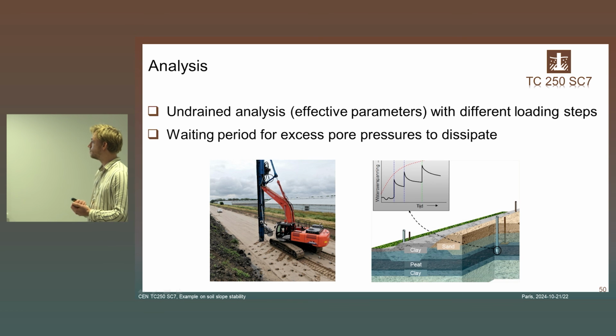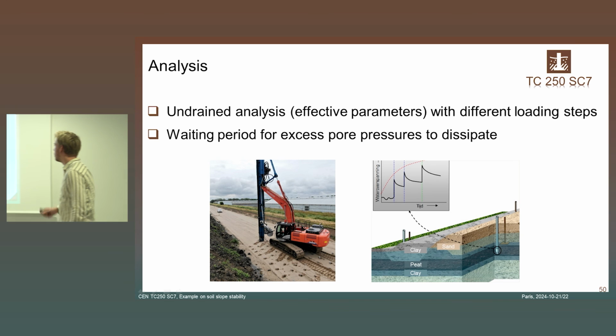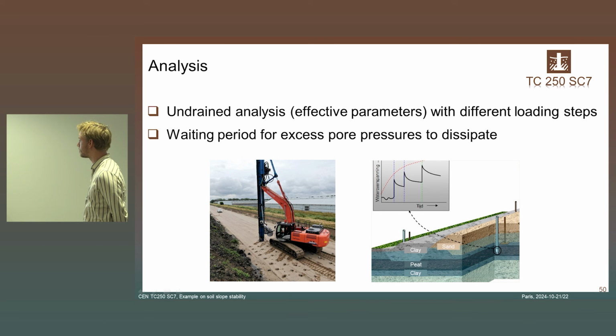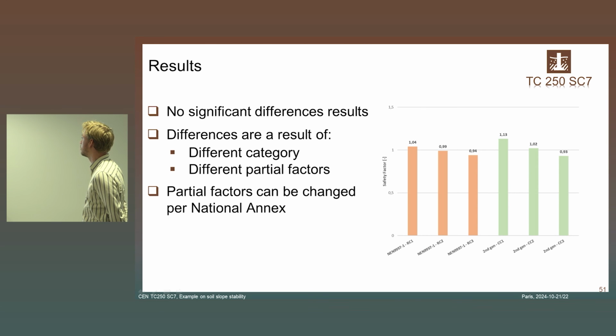So those settlement requirements are quite strict. That's why the overheight is used, and as can be seen in the picture here, every time a meter of sand is applied, you can see that directly in the excess pore pressures. If your structure or your slope is unstable, add some weeks of waiting time, and you're good to go, or adjust drainage measures, for example.